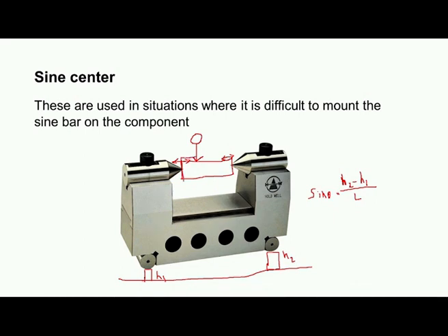So, we should place the tapered component here between centers, and then we should adjust this height difference H2 minus H1 till the dial indicator reads 0.